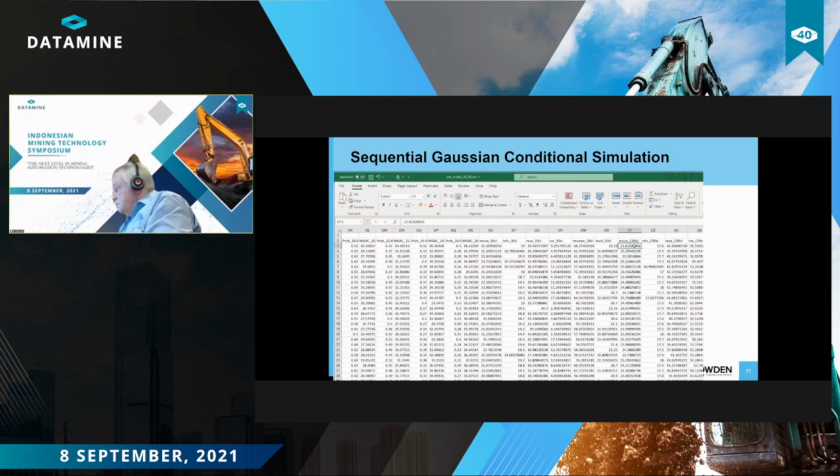So this data represents all of your simulations and the relevant statistics that go along with it, available to you here in spreadsheet form and available for any post-processing that you wish to carry out. A very useful statistic that we can calculate from this information is the coefficient of variance, or the CV, which is simply the standard deviation divided by the mean. And this gives us a value that we can compare block with block, and gives an indication of the precision or confidence of the estimate in a particular block compared to other blocks.